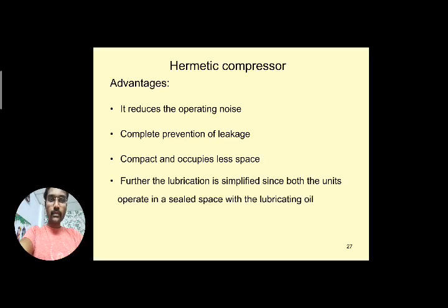Next, lubrication is simplified since both the units operate in a sealed space with the lubricating oil. Lubricating oil is also provided in that particular space. And there is effective cooling of motor windings. Lubricating oil is present, and also the refrigerant vapor is making contact with the windings. Due to the low temperatures, both the lubricating oil and the motor windings get cooled. So effective cooling takes place in this hermetic type of compressor.